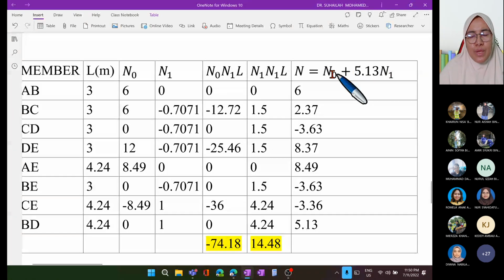superposition. If we use equilibrium equation, that means we have to repeat calculating member forces using method of joint or easy method. But we actually have the easiest way, and the easiest way is by using principle of superposition. That's why I asked in the quiz question earlier. The final step in beam and frame is reaction. After reaction you can continue to draw bending moment and shear force diagrams. But when we analyze truss, the final step is member forces.